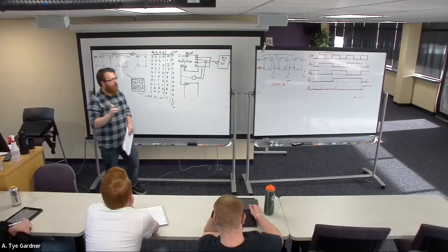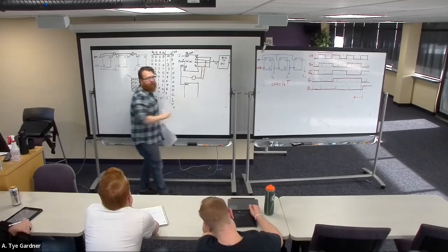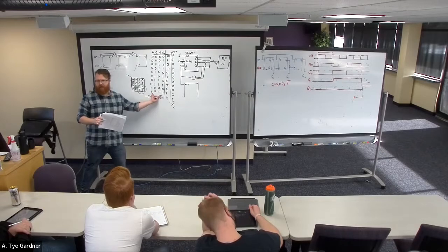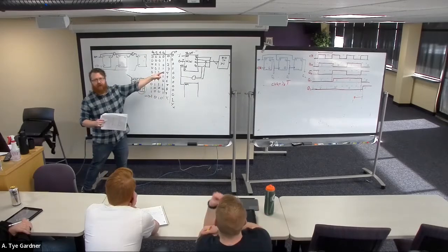If we were designing for synchronous load, we would attach this to Q0, right? Because then we would want the reset here at 9. But this is the design for asynchronous load.